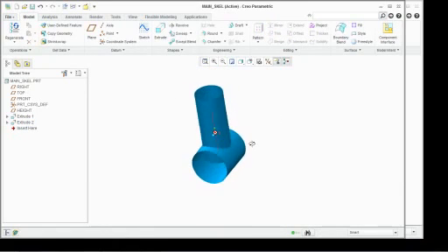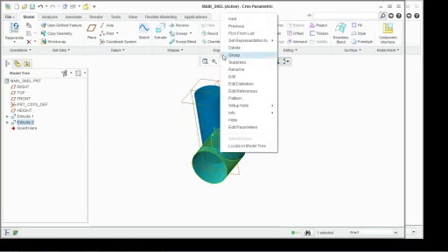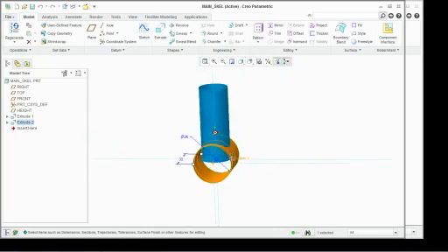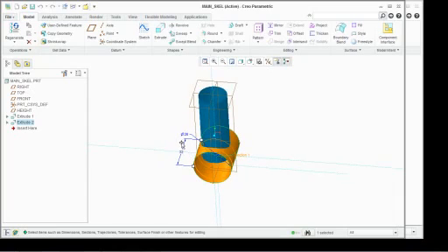So there we've got the basic skeletal structure of the engine. I'm going to go in and add some datums to it, create some planes. But if you notice, I can come in here just like any other solid geometry and edit, and it's just like a normal extrusion. I can change the length of it or the diameter of it, just the same way we always have been able to.